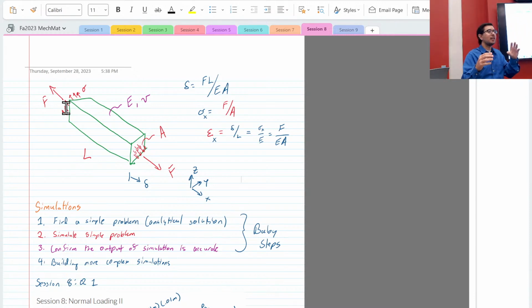So how do you calculate the change in height, or the change in thickness of the beam that's being pulled? Yeah, using Poisson's ratio, right? So you can calculate it out, and you should have an estimate for what it should be. Poisson's ratio is the negative of the latitudinal strain over the longitudinal strain. So you can figure out how much strain you should have in the vertical direction. And if I know what that strain is, and I need to know how much the thickness changed, I multiply by the original thickness. And that should be a negative number, okay?